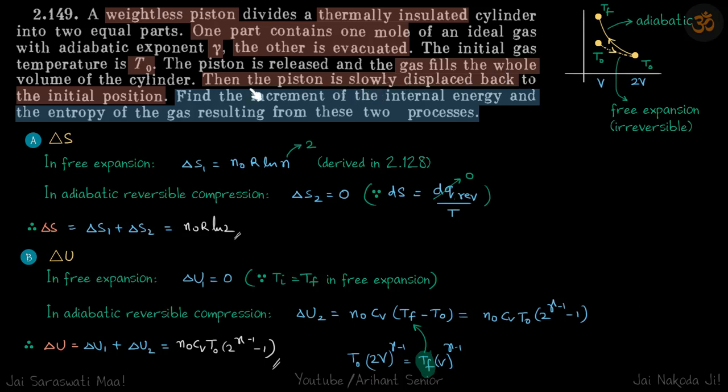After that, the piston is slowly displaced back to the initial position. So the final volume is the same as the initial volume. And because the cylinder is thermally insulated, the process has to be adiabatic. So from here to here, the process is adiabatic. So this is the whole process.